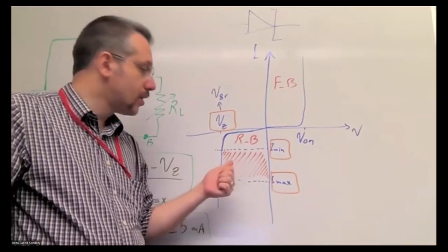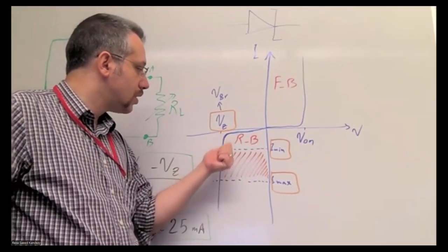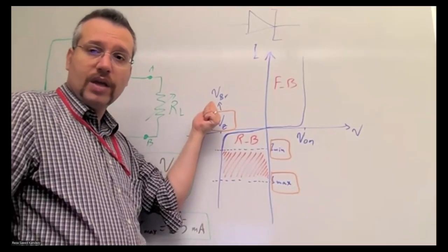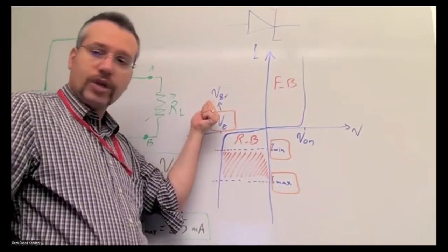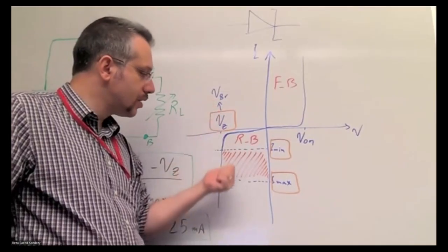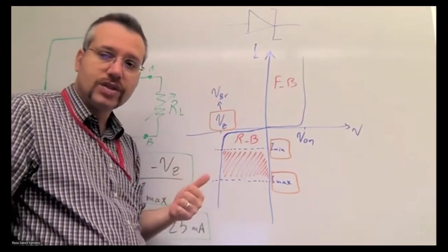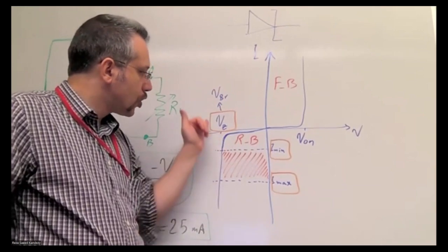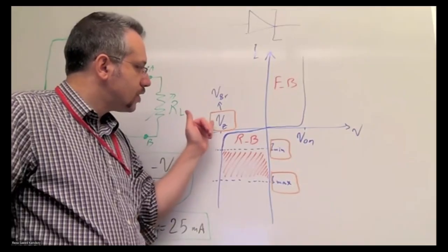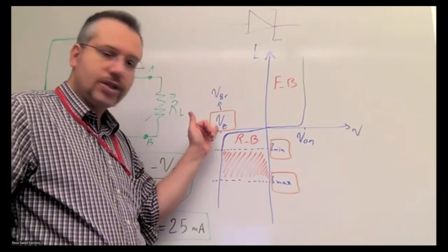But not only reverse bias, we normally use it in the region of the voltage breakdown. Okay, we already said that the breakdown voltage is a dangerous voltage for a regular diode, but in the Zener diode, because of the physical characteristics, we are going to work on the breakdown voltage, which we call the Zener voltage.